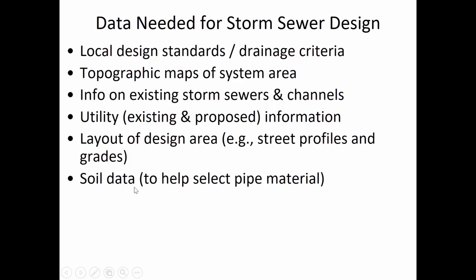And knowing the soil type is important because some soils are incompatible with pipe materials that you may wish to use. Like if you have soils that have been contaminated with acidic contaminants, then that may cause corrosion of metal pipes, for instance.